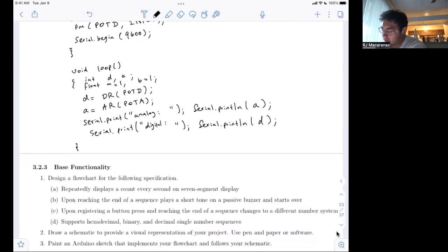So then what we want to print is the calibrated voltage reading, and then we print out this voltage reading, which is M times A. This is going to be an asterisk, plus B. And you might have to convert A to a float, so let's just start off by defining them as floats anyway. So we print out M times A plus B.